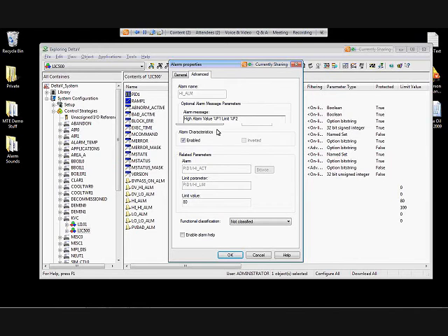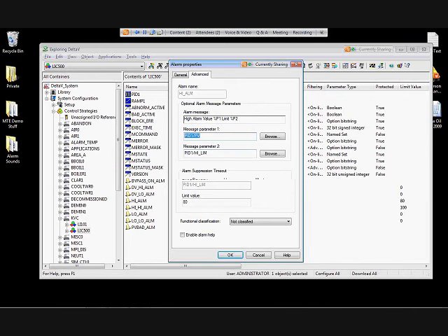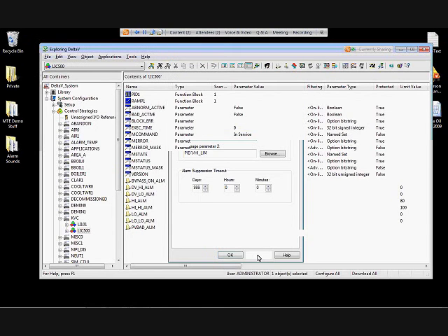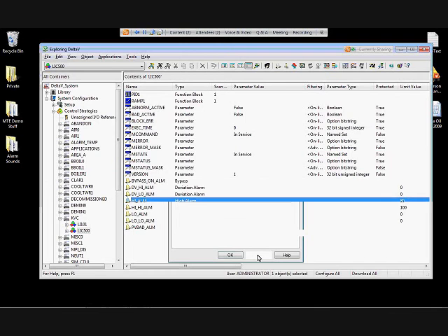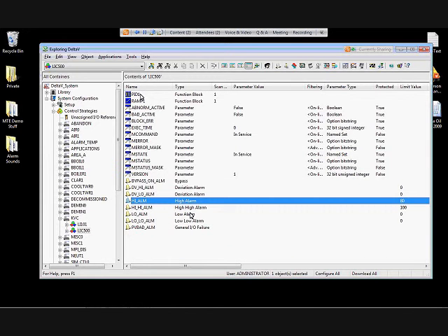Also, under advanced settings, we'll see that there's no shelving going on here. This thing has the DeltaV default of 999 days here, so I suspect that we're not doing shelving with this alarm. If it is a chattering alarm, that would suggest that maybe the hysteresis, on delay and off delay weren't properly set. Let me just take a quick look at those.